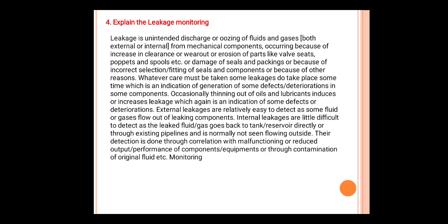External leakages are relatively easy to detect, as some fluid or gases flow out of the leaking components. Internal leakages are a little difficult to detect, as the leaked fluid or gas goes back to the tank reservoir directly or through existing pipelines and is normally not seen flowing outside.